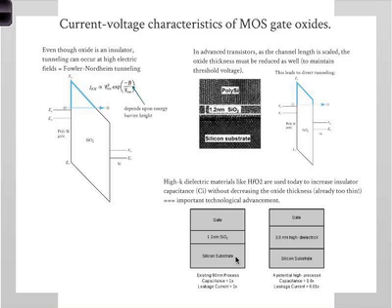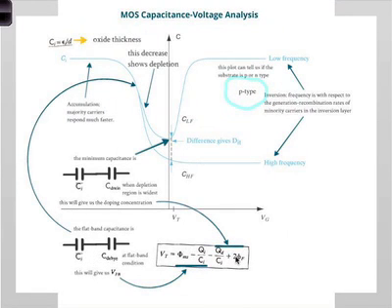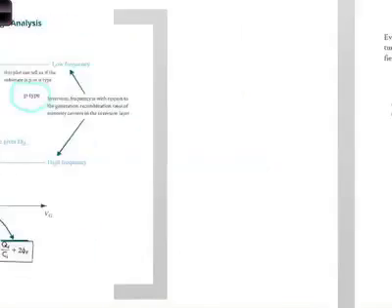Okay. Now, there's another advantage, by the way, to the capacitance curve. The advantage is that you don't actually have to wire anything up. Right? You can have a device which is not connected to anything here. Just apply a voltage here, with respect to the body, right? You apply an AC signal. So it's a much simpler experiment to do, rather than sticking on an oscilloscope, right? So it's much simpler to measure as well.